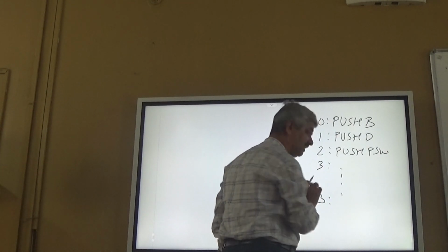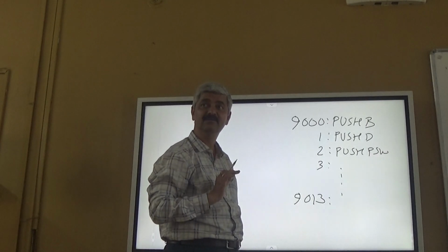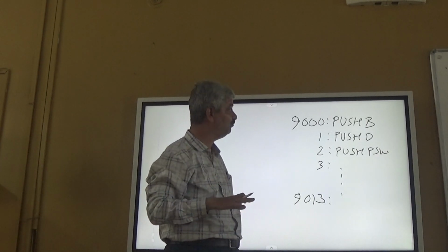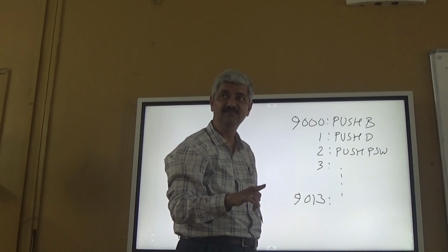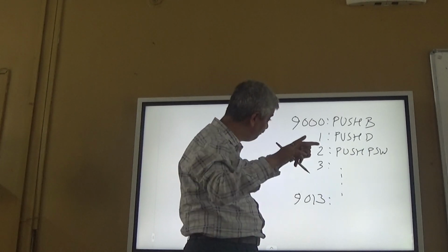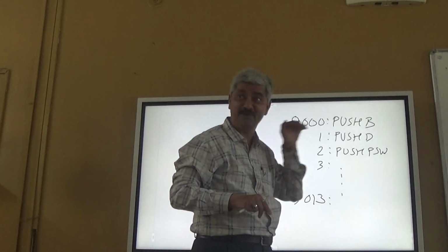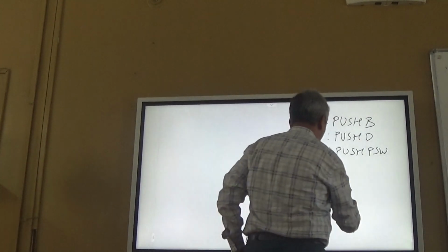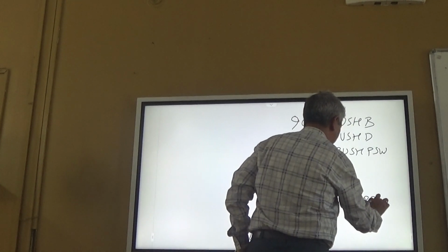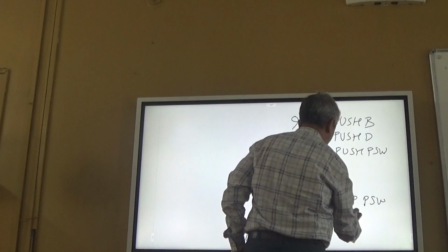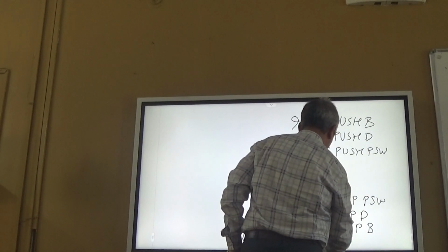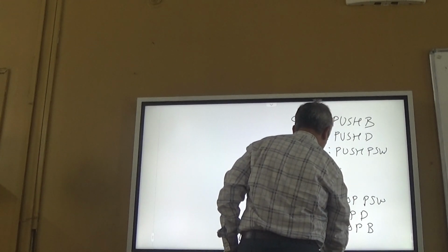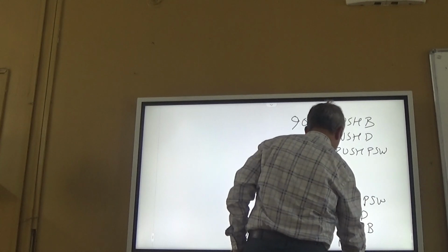I will pop them. Pop PSW, pop D, pop B. I am pushing on the stack and popping in the reverse sequence. And then return.